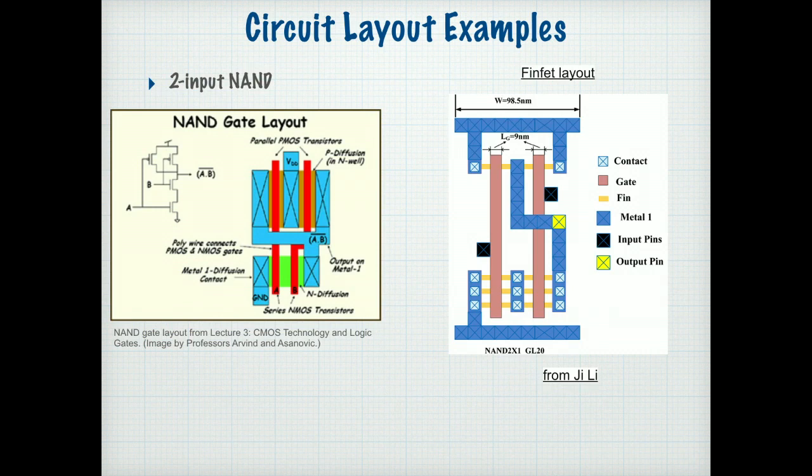And here the colors are similar to what I had used previously. These were kind of the standard colors, at least for some folks. Here polysilicon is the red. The metal is in blue here, and the N diffusion is in green. And there's another type of diffusion, P diffusion, that we're going to use to make the complementary transistors, as we'll talk about later.